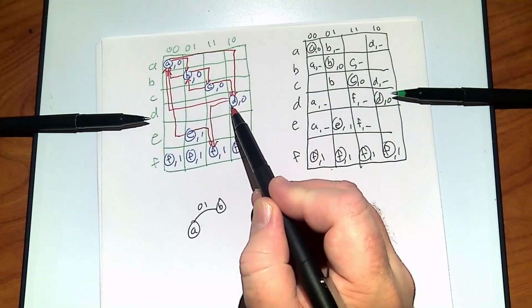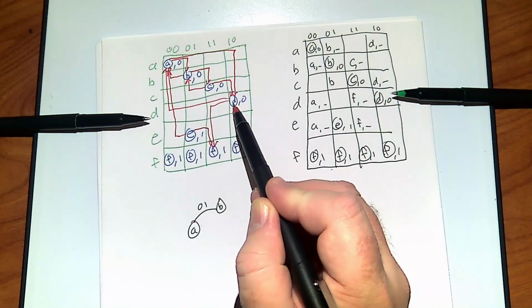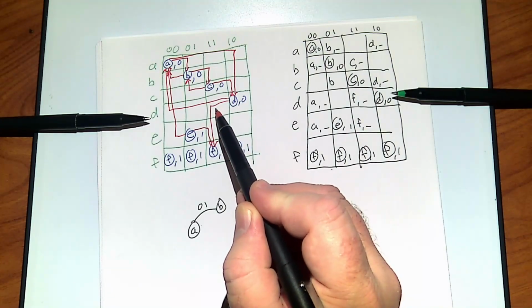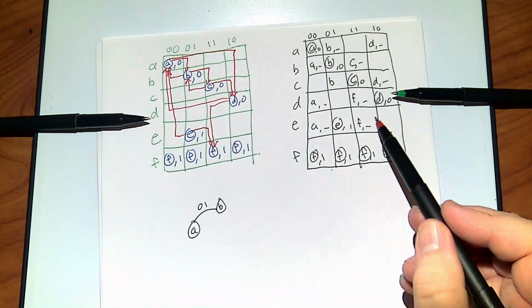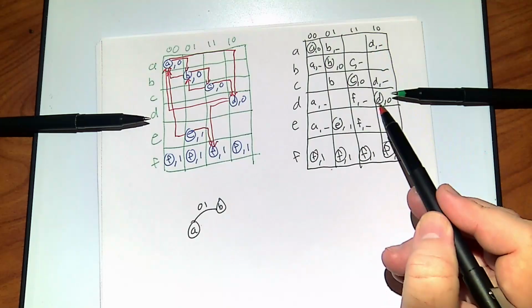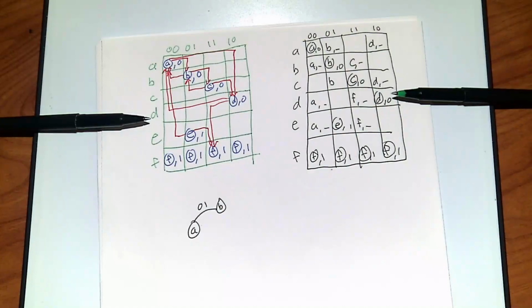At some point, somebody can transition my input to 1, 1. So I'm assuming I was stable at D. I went to 1, 1. What do I do? Do I stay at D? Do I go somewhere else? Well, the arrow tells me I go to F. So I was stable at D on a 1, 0. When I go to 1, 1, it tells me go to F. So all these letters are doing is encoding those arrows. I've just turned the arrows into a letter code that says, to what new row does it jump to? That's the vertical part of the arrow. Does that make sense?